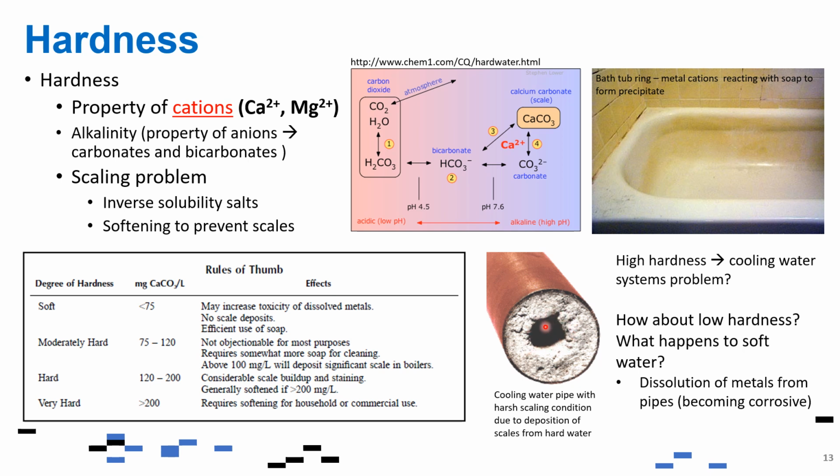So in this system, because of the presence of scales, you need to compensate for the lower area. You have to pump more water in order to have the same flow rate as the original. Once you pump more water, you're using more energy and adding more cost to the system, so it is more expensive because of the extra pumping power.